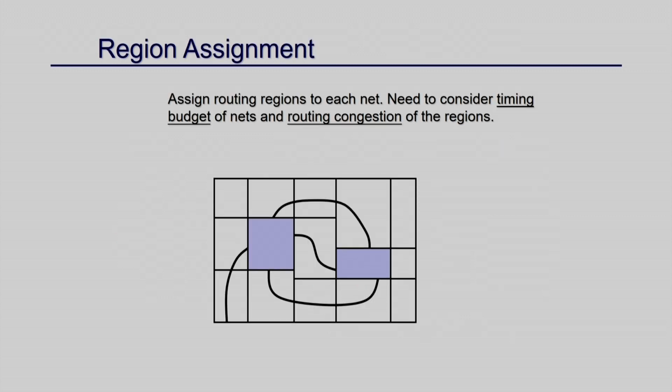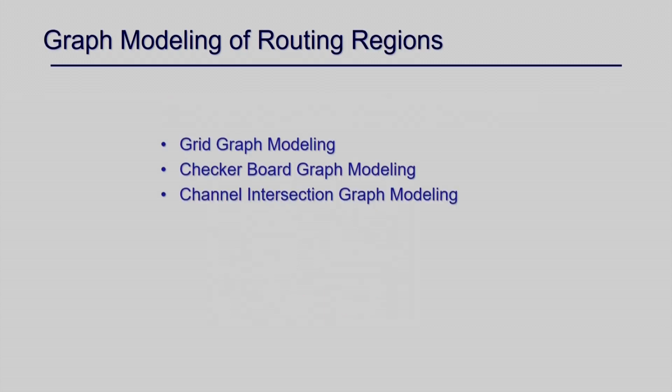After that, as I mentioned, the first is region definition: you define how many channels and switch boxes there are. Then you make the actual connections and do the region assignment. This particular net goes through this switch box, or this channel, something like this. So, you have to assign channels and regions or switch boxes to each net, which is called region assignment.